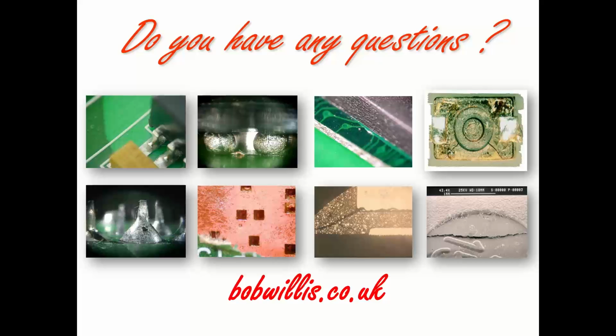Right, the question is, should plastic through-hole parts be assessed for MSL? If you're just going to be doing wave soldering or selective soldering, I would generally say no. Where you are going to be doing pin-in-hole intrusive reflow, so you're looking at 220, 230, 240, maybe even 250 degrees Celsius going through a reflow process, then yes, you need to speak to the supplier, and do some trials yourself to make sure they're compatible.